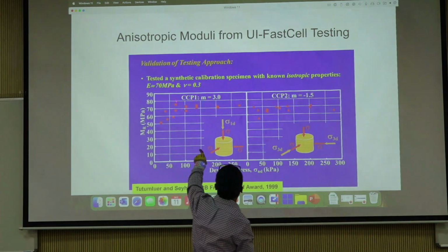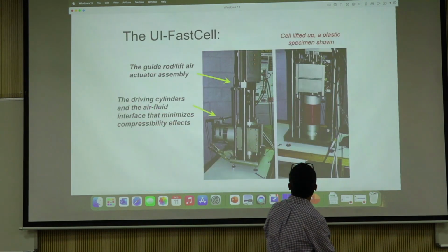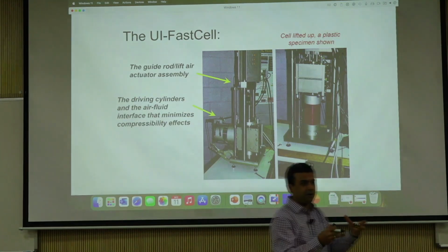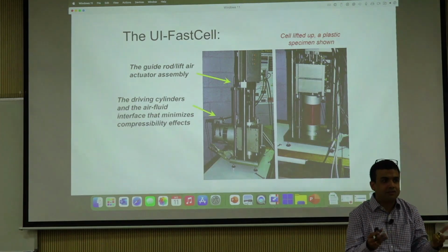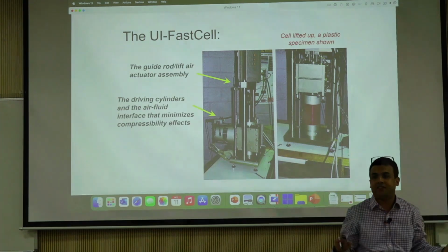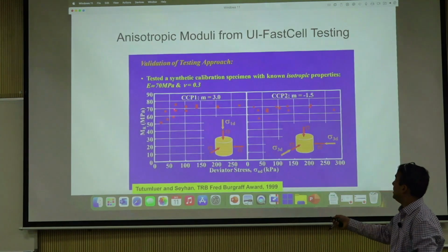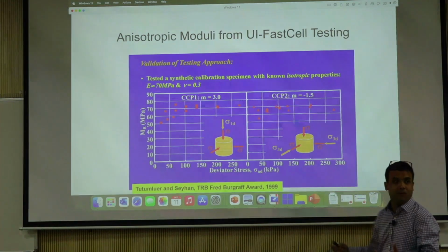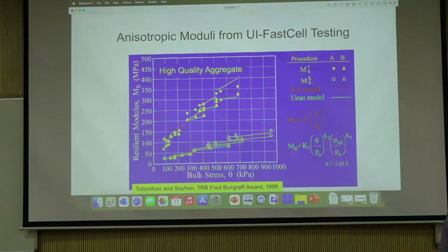And I actually did the exact same thing, and this is on the red specimen. This specimen, it's plastic. It's like not plastic, like synthetic rubber or something. So is it dependent? No, it's constant modulus. So irrespective of which way you pulse, you should have the same, and it's isotropic, right? That's what this data is saying. You're proving it that either way you pulse, you measure the same thing, right?